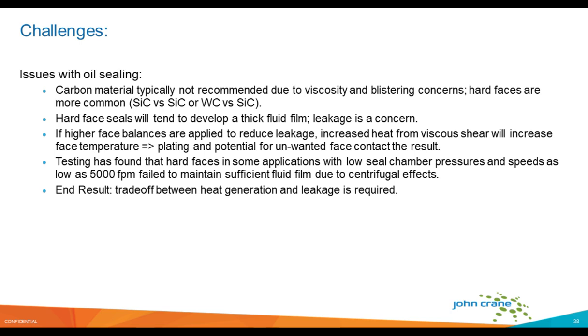So when we look at oil sealing, there are some issues and challenges we have to overcome. When Jack was talking about seal faces requiring full fluid film lubrication, and we want to manage heat generation and leakage, well, in an application that's very high speed with oil, it becomes very unique and difficult because of some of the limitations around conventional end-face mechanical seals.